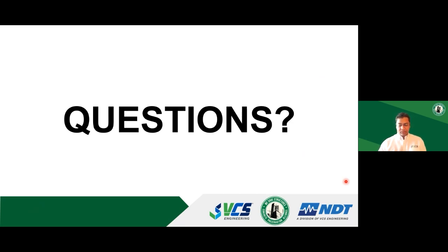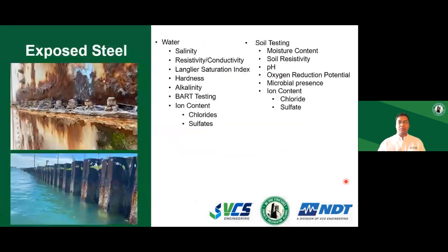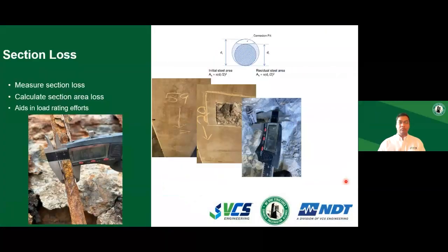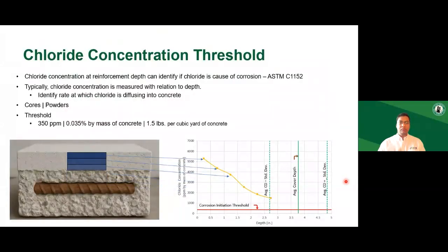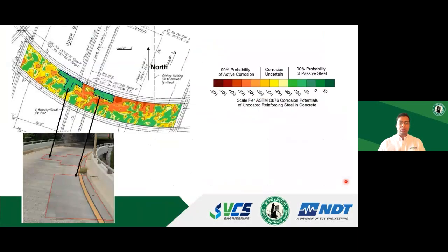Yeah, I've also seen concrete resistivity testing used on those types of structures. It's just an indication of corrosion risk beyond a corrosion potential test. Right. We also had a question about the one slide we had of the off ramp, where you showed the passivity of the repairs, and you had the active corrosion around the repairs, and you mentioned the halo effect. There was a question about mitigation strategies to deal with that risk of corrosion.